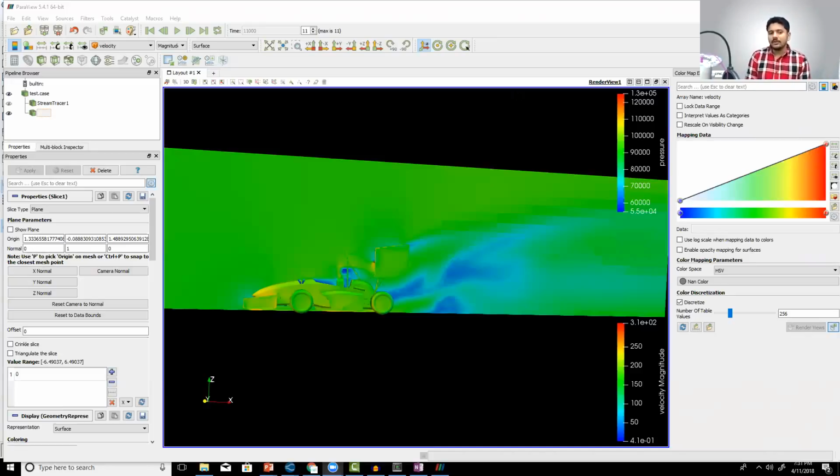How to fix the meshing type and its size? That's a great question. As far as the size is concerned, Rishikesh, that is where the Y plus criterion needs to be followed for external flows. As far as the meshing type, that's very tricky.